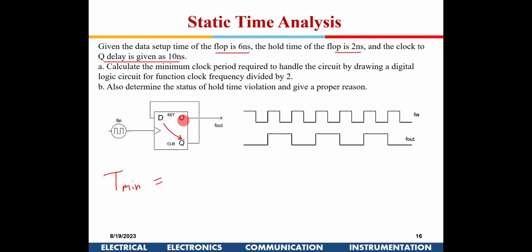Please don't get confused. In many circuits when we talked about flip-flops, there is a small amount of delay between Q and Q bar itself. Q bar might be coming slightly early or slightly later. So let's not get confused with that. When we take a flip-flop as a single block, we don't try to distinguish between Q and Q bar. We will assume both Q and Q bar are available at a time given by TCQ. So this is available, and then that needs to come here.